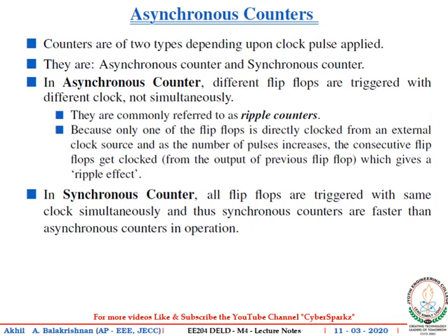Counters may be asynchronous counters or synchronous counters. Asynchronous counters are also called ripple counters. A ripple counter is the simplest type of counter, easy to design, and requires the least amount of hardware. In a ripple counter, the flip-flops within the counter are not made to change states at exactly the same time, because the flip-flops are not triggered simultaneously. Ripple counters are also called serial or series counters.